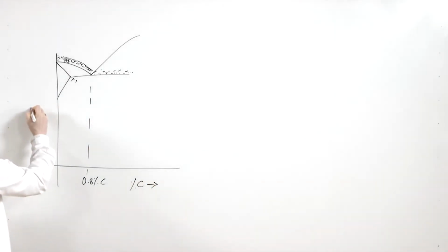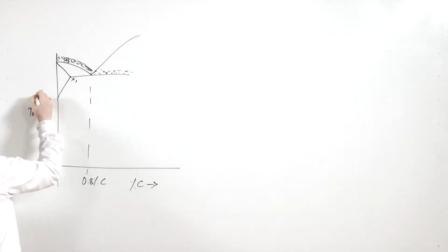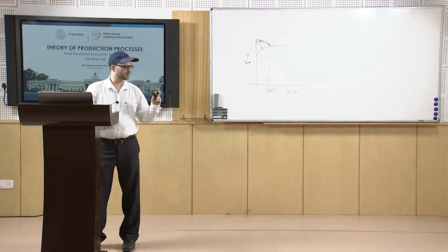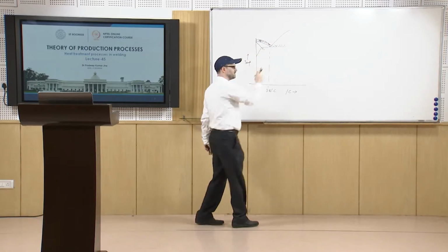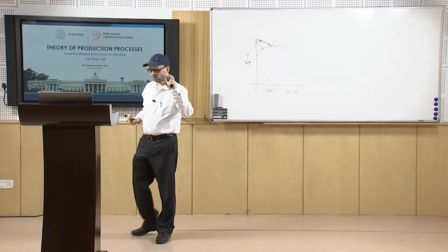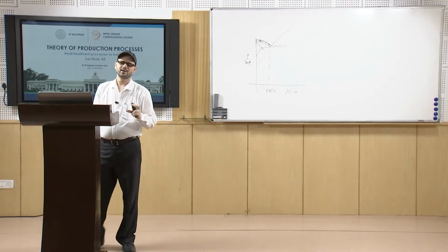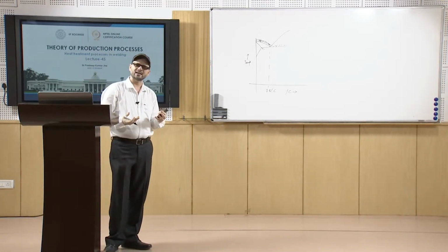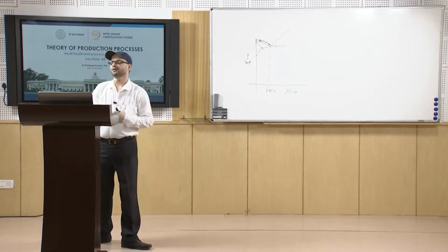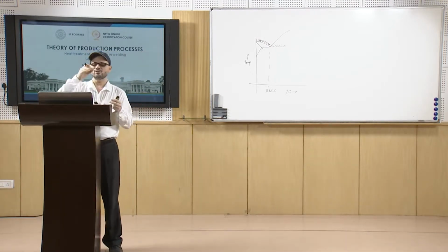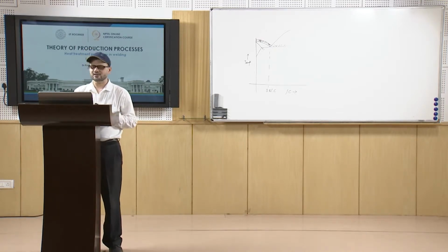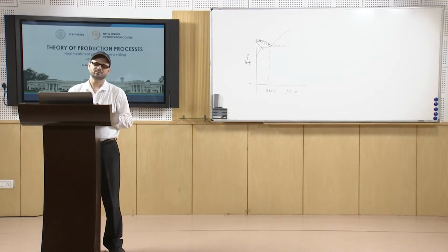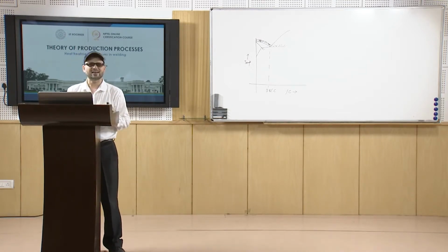Okay, and this is your temperature. So, what we do is we are heating to this temperature, and after that we are holding there. Now, holding time will normally depend upon the section thickness of the material, and then after holding we are cooling slowly in the furnace. So, depending upon that you will have different types of annealing purpose.